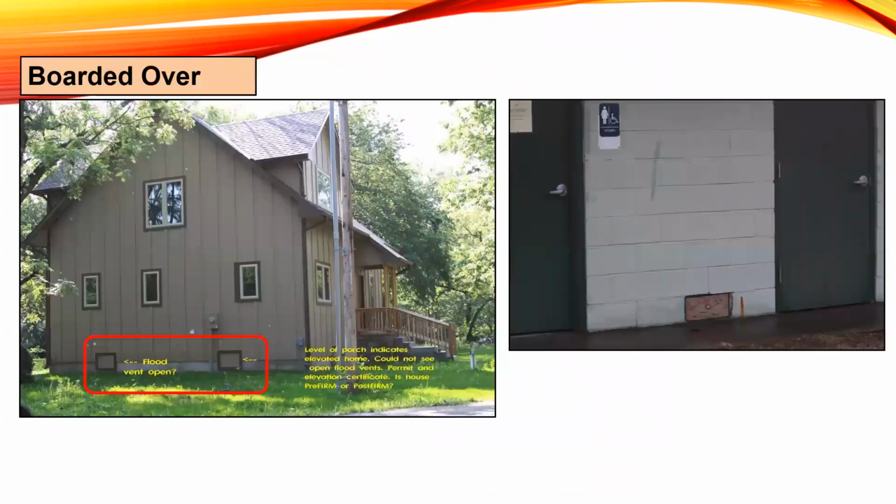So another issue that commonly happens is that people will completely cover their flood openings for different reasons. Sometimes they say the floors get cold in the winter, or I hear a lot about pests or raccoons getting into the flood openings and causing issues.